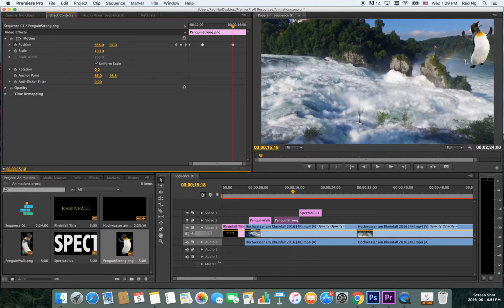Okay, this is the keyframe that we defined before. So now I will press the right arrow key once more. Look at this difference. I will move the timeline a little bit so that I'm outside the keyframe. So I would click here and add another keyframe. So now I add another keyframe here, and that asks it to stay in here for one frame.